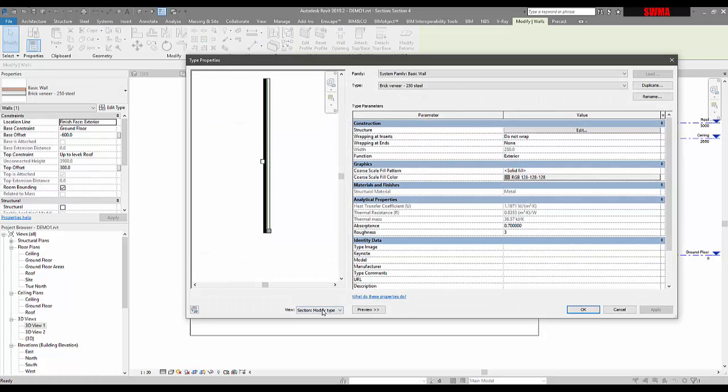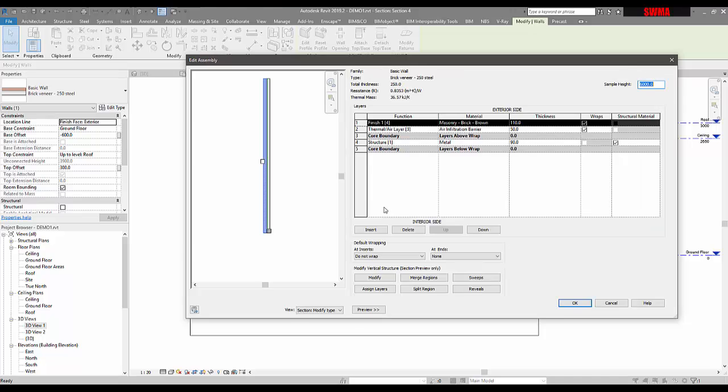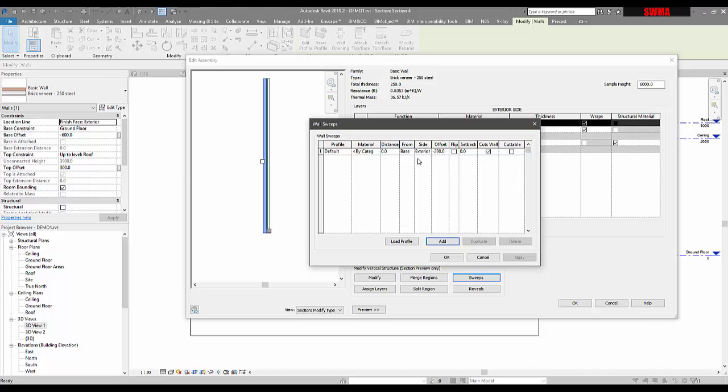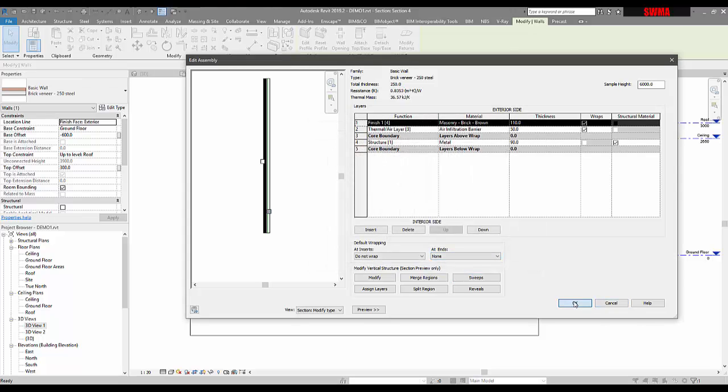So all I did before, if you're wanting to see this all done again, we'll go and do our sweep. It is sitting inset from the wall because I'm faking the item at the moment. 600, go apply. Allow for the floor slab, which I'm going to say is 150 for the interior.